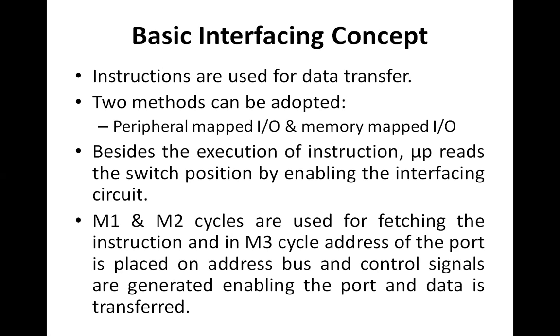Meaning thereby, if we want to read, the data will be read from the input device through the IN instruction and stored in the accumulator. And whenever we want to write the data, the content of the accumulator is copied into the output device.